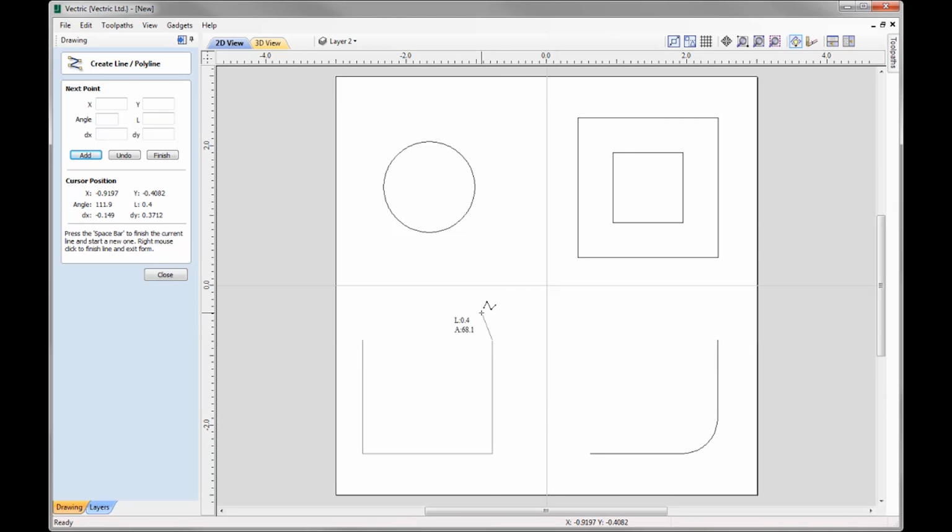I can also do angled lines, so you can see I can follow along those angled extensions, making it a lot easier for me to create accurate geometry there. So I'm just going to click that in place at the center, so it's found the center object bounds for the object that I'm currently drawing, which is handy. And then we'll just bring that down over here to join that up.